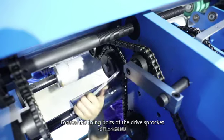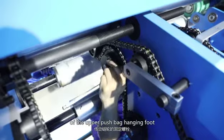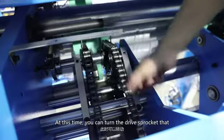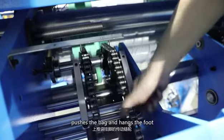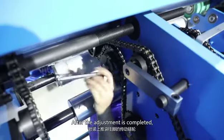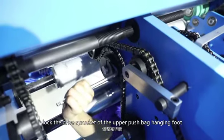Loosen the fixing bolts of the drive sprocket of the upper pushback hanging foot. At this time, you can turn the drive sprocket of the pushback hanging foot. After the adjustment is completed, lock the drive sprocket of the upper pushback hanging foot.